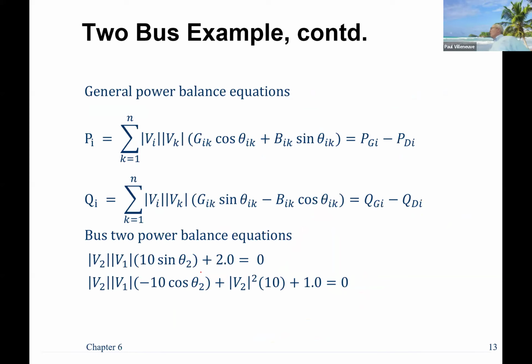All right, so let's go ahead and start writing our equations. So I'm writing delta P2. I know that I is going to equal 2, right? And N is going to be equal to 2, so it's a total of 2 buses. So I know that this right here can become a V2. That's fixed, right? K is the one that varies, not I. So I can actually move this right out front of the equation. Now I start out with K equal 1, so I have V1.